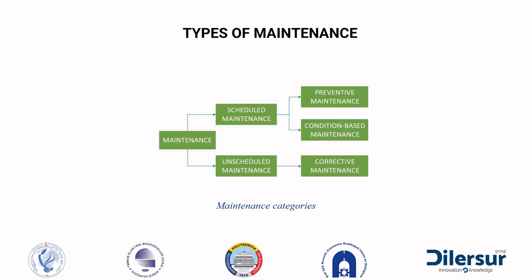The main activities under preventive maintenance include checking of mounting structure integrity, module cleaning, hotspots detection, junction box servicing, inverter servicing, checking the cabling connections, checking the various supporting and auxiliary components of the solar power plant system, checking the earthing protection, and vegetation control.